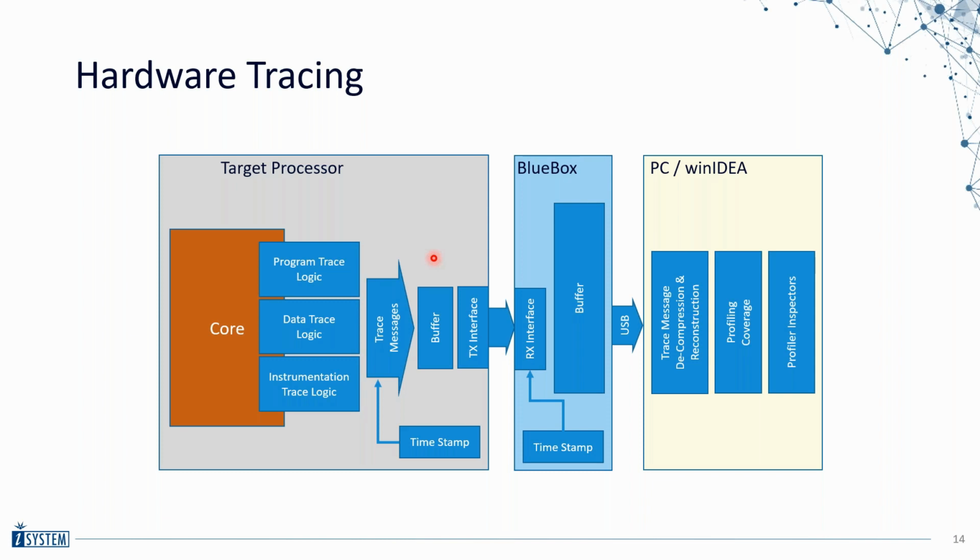If you don't have an on-chip trace buffer and you have the JTAG interface, there's no way to do a pure hardware trace. Instead, what you need is a streaming interface, like Nexus, for example. If you don't have that on your PCB, the solution is usually to use a so-called emulation adapter. That means you replace the microcontroller on your target with a soldering unit, and then you put the emulation adapter onto the soldering unit.